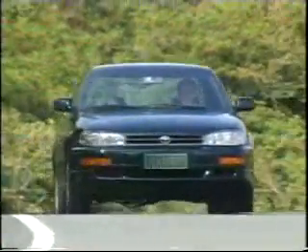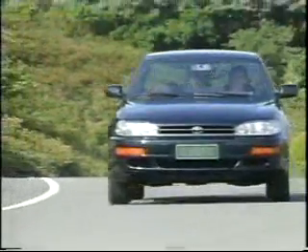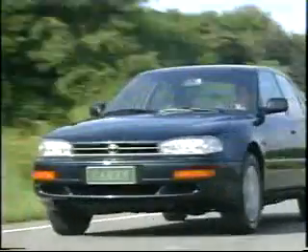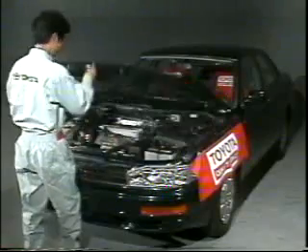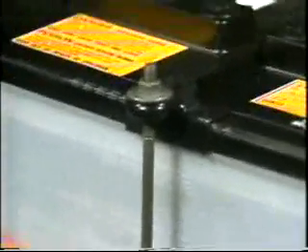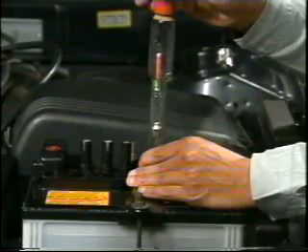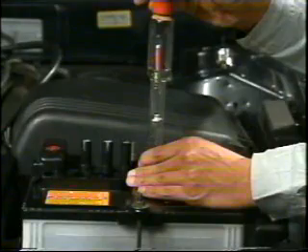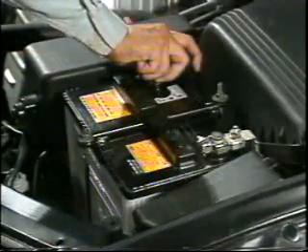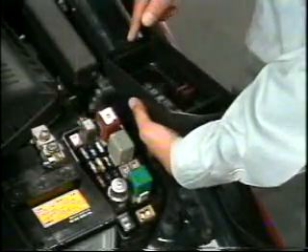Another problem is that the battery cannot be fully charged because the car usually drives only short distances. You should make sure of the following before investigating the charging system. Is the electrolyte level and the specific gravity of each cell of the battery correct? Are the battery terminals, the fusible links, fuses, and connectors connected correctly?